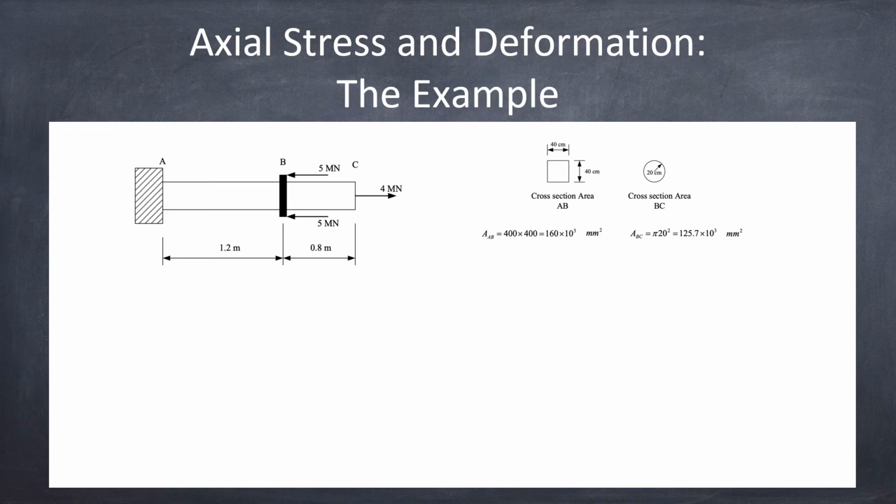And then let's look at this one. As I mentioned before, we need the axial force. But in this case, if we look carefully, we don't really need the reaction at point A, because we can cut the structure and look at the right-hand side of the picture instead. So that's what I would do.